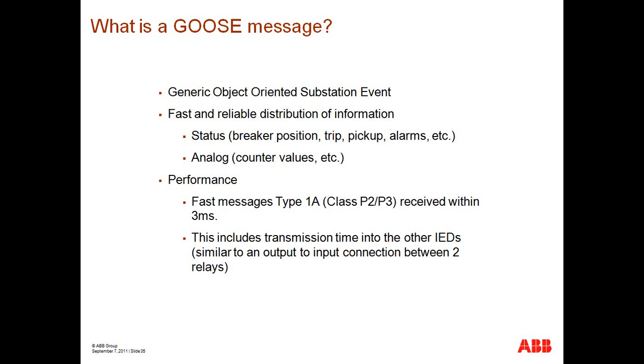On 61850, that exchange happens within 3 milliseconds, and the gain in performance is thanks to the fact that these are communication messages that are properly framed. There are checksums, there are integrity checks, so you really do not have any type of noise concerns at that point. If the packet is properly structured, then it's being trusted for that change. So there's no need to further delay the sequence of events that a particular GOOSE message generates.